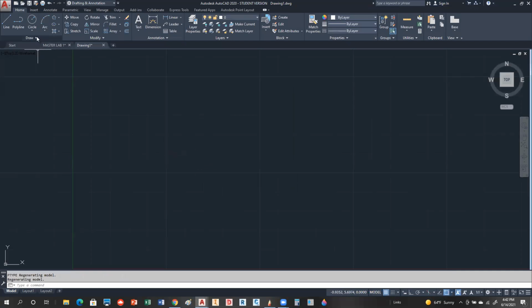So if I go into here and generate multiple points, there it is. PD mode is set to 2. PD size is 0.5. So as I pick points on my screen, notice what I'm getting. I'm just getting points like this, and wherever I place them, that's what I get. These guys all happen to have the same Z value because I'm not changing my Z. I'm working on that 0 plane. So if I listed them, that's all they would have.